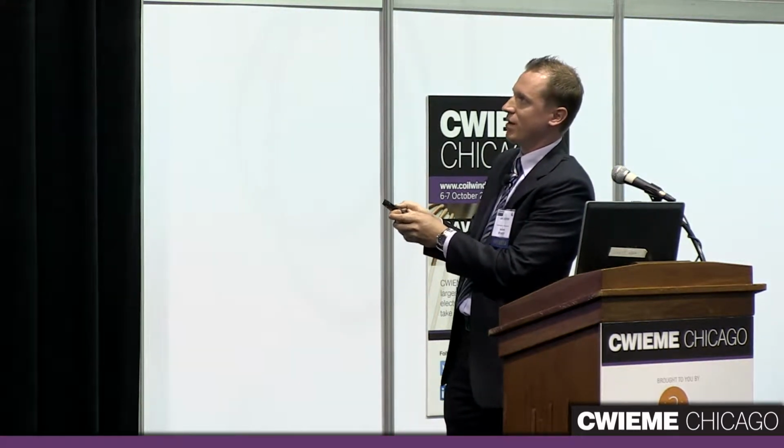And now we have to take a look at the mechanic part of such a model. For that, we have to calculate the torque. And this is really simple. It's just the power balance of this equation, because the mechanic power is just the sum of that. And mechanic power is torque multiplied with speed. So if you want to get the torque, it's the power divided by the speed. And here omega is the speed. So just keep that in your mind, add that up, and what you end up with is this equation. This is just the torque. It comes from the power balance of the electric equation.